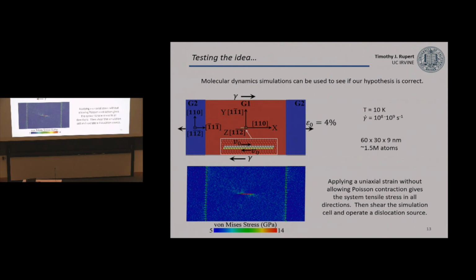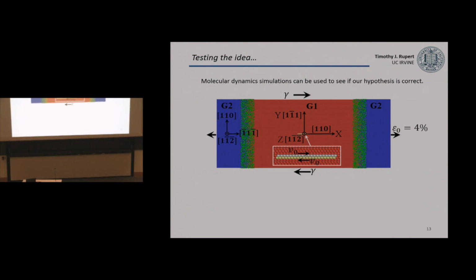And there are some details and specifics about what we were doing. There are often some limitations on these types of models. We can only model a certain number of atoms. We can only model a certain amount of time, which means we have to use relatively wacky strain rates. But it lets us sort of isolate the important features. And most importantly, it lets us change what this grain boundary structure looks like. So we can go in, pause everything, stop, take the boundary, melt it down, freeze it in, give it an amorphous structure. And we can do that with different thicknesses.